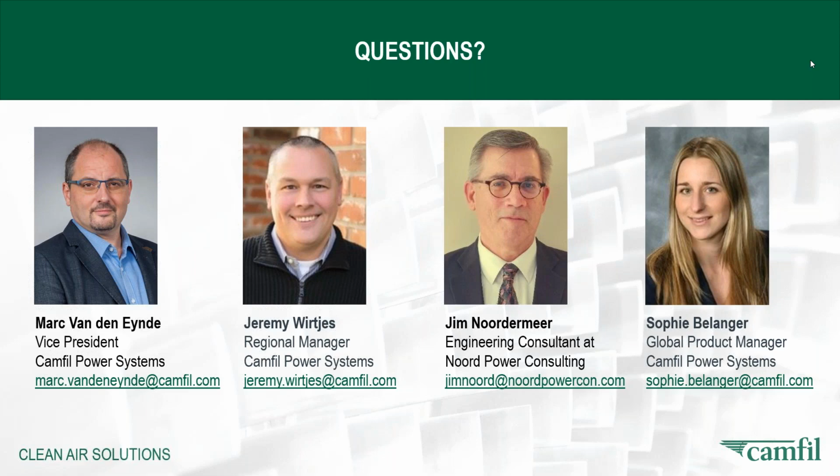Yeah, and in general, we just need the coordinates of the location where you're situated, or where you plan to have your new project, and we can have this benchmark overview at that point already. But as suggested, for a new project, yes, the recommendation would still be to make a more local long-term analysis to make sure you understand your environment in detail, and you know exactly how you should protect your gas turbine with filtration solutions.